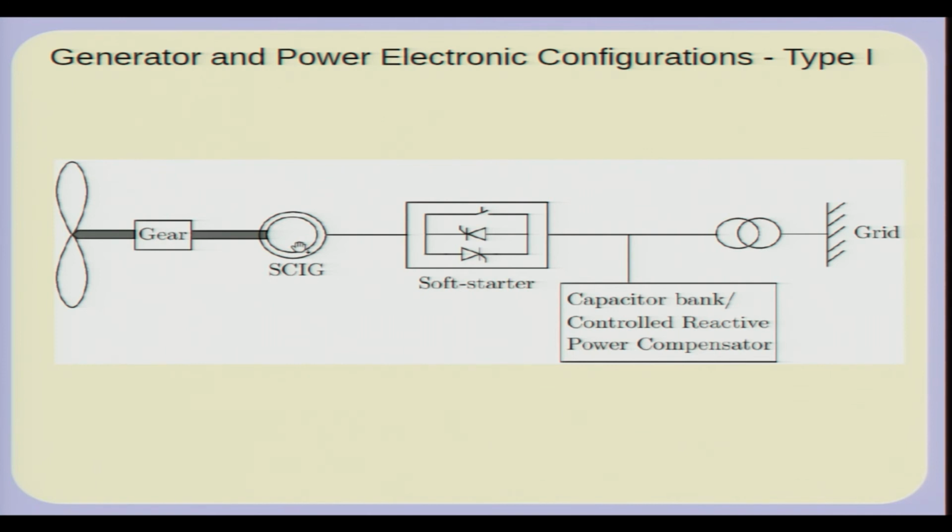As I mentioned, for large induction generators, typically the slip is small. If you go from 0 torque to rated torque of the machine, the slip variation is very small. So, for all practical purposes, the squirrel cage induction machine is almost a constant speed machine. So, the characteristic of the machine would be vertical in that characteristic of the turbine which I showed some time back.